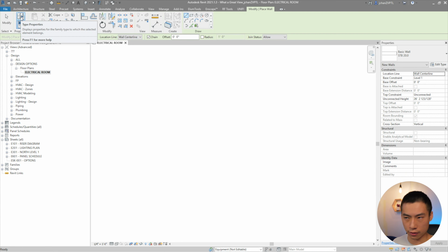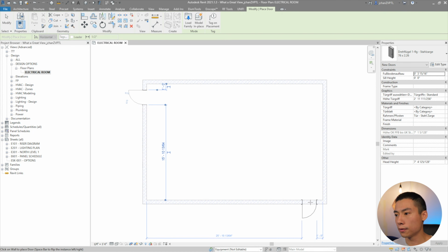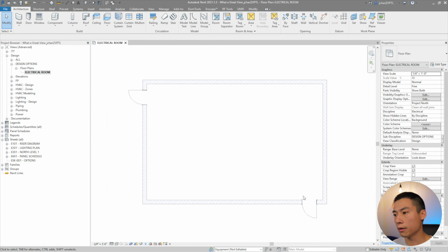Okay, so let's just jump right into Revit. This is a popular way that I actually do my design because Revit allows you to sketch out a layout really quickly and then tweak it into options like this. So let's just start by drawing ourselves an electrical room. So let's do 30 by 20. Okay, put that over here. And then we'll add some doors at the extremes. Whoops, let's flip that around. Perfect. So here's our electrical room and let's start putting some equipment in here.